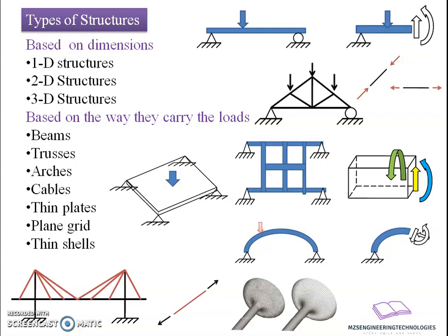In case of a two-dimensional element, the effect of the stresses and forces along one of the dimensions is neglected. For example, in a planar structure, the effect of the forces along the thickness can be neglected, thereby we idealize it as a two-dimensional structure. Examples: slabs, curved beams, domes, retaining walls, Hume pipes. In case of a three-dimensional structure, we have equal weightages of all three dimensions towards the contribution of the loadings. For example, columns and footings.